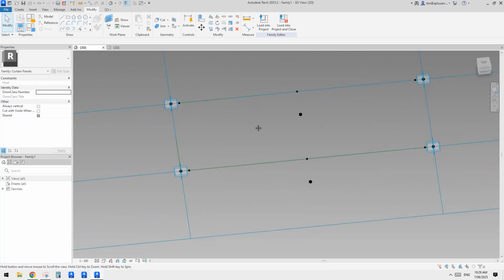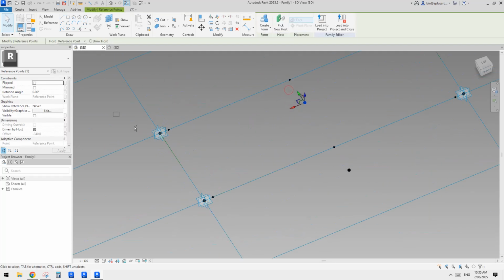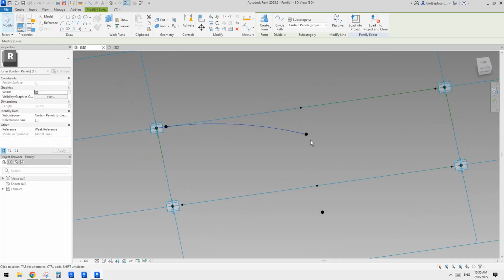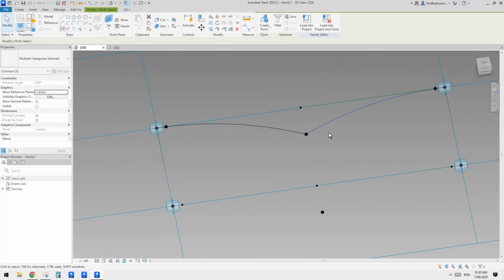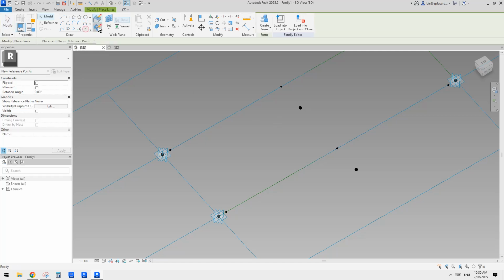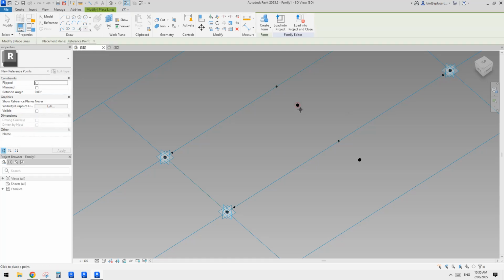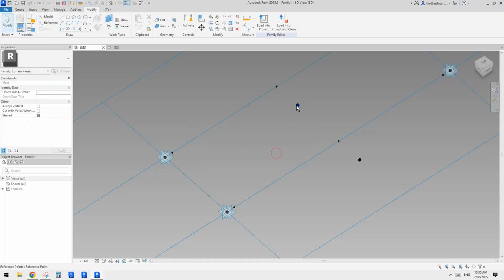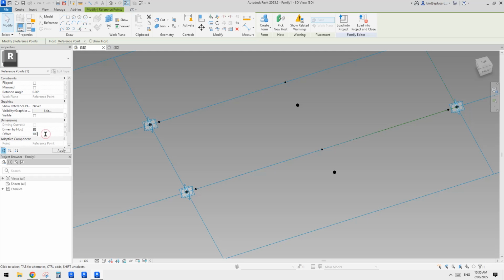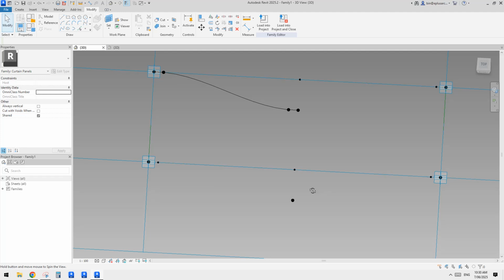These are separate panels. So now we need to create a line like this. Which means if we create a spline and do another one, you'll see it's not going to be continuous, right? So what we need to do is also very simple. We just need to place a point onto a vertical work plane on this point, and then give it a little bit of offset. For example, I'll give it 100 offset as well, and then if we select 1, 2, 3, 4, now that's what we have, right?